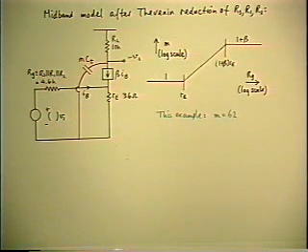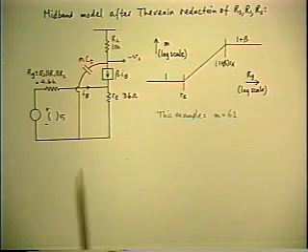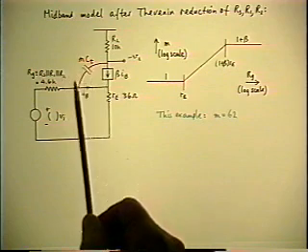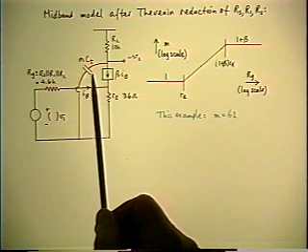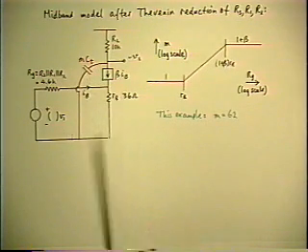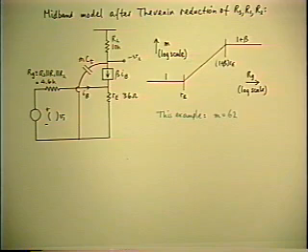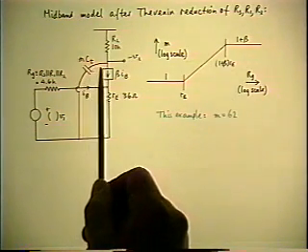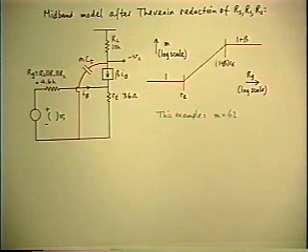Now, you've heard about the Miller effect before, and you usually think of it in terms of this interpretation, where the effective value of the capacitance is multiplied. You may also remember the Miller effect in the sense that the value of the multiplier is usually expressed as 1 plus the voltage gain of the stage. If that's A, then the effective value of the capacitance is 1 plus A times CT. Does that sound familiar? Is that the way you use the Miller effect? You notice I've avoided saying that.